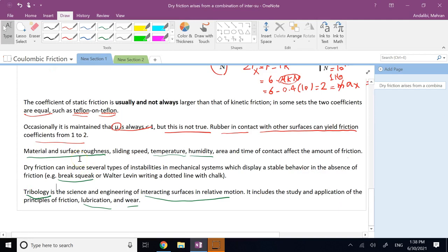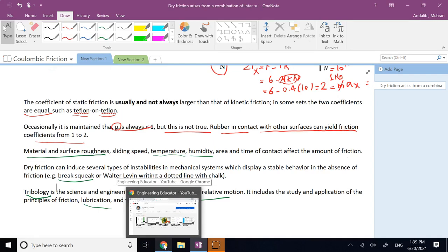Well, the reason is when you apply the brake and the braking pad is applied to the moving wheel, the pad gets engaged, and then due to oscillations in the friction force and so on, the contact is reduced, so they might get off again and disengage, and then again engage and disengage. So this engagement and disengagement and relative motion between the surfaces is basically set and reset several times, and that causes structural vibrations in both of them, and that will cause brake squeak.